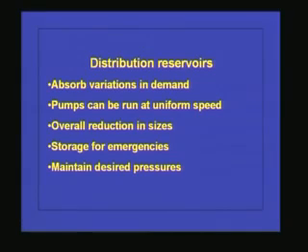Now what happens with this is, it will actually reduce the sizes of your pipes, it will reduce the sizes of your pumps, it will also reduce the sizes of appurtenances and all those things. Because of this reduction in the sizes, it also can reduce the size of your treatment plant, and because of this reduction in size you can achieve economy. Distribution reservoirs can also store water for emergency purposes, and they can be used to maintain approximately uniform pressure throughout your distribution system. This we will see later.